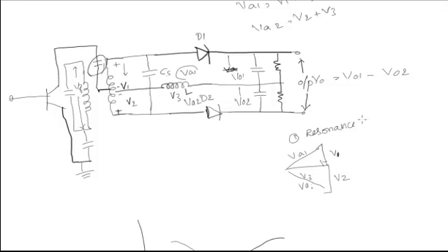And the other case is off resonance. In off resonance, we have two different conditions that depend upon the frequency levels. When the input voltage is off the resonant frequency of the tuned secondary, then the phase position of V1 and V2 related to V3 will be different from 90 degrees. Here, if the input signal frequency is above the resonant frequency, then the phase relationship between V3 and V1 will be 135 degrees. And this is shown like this.